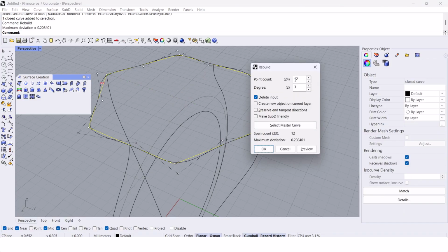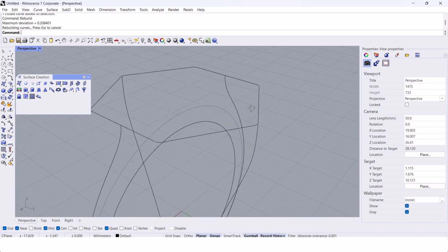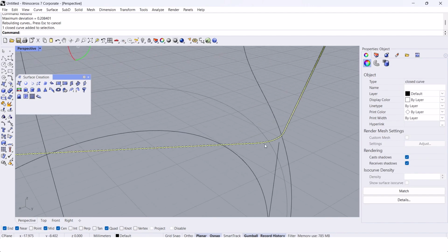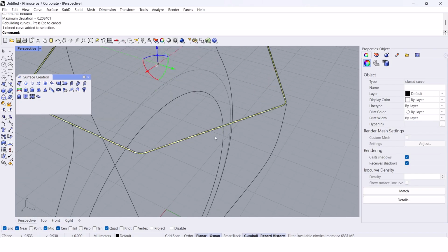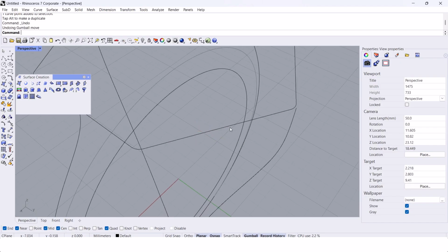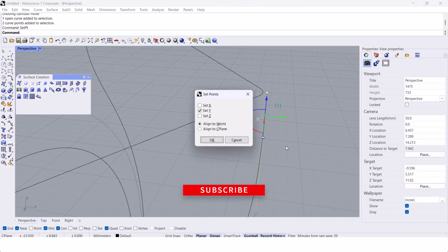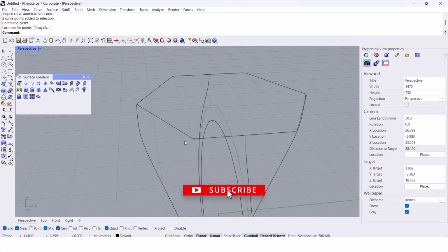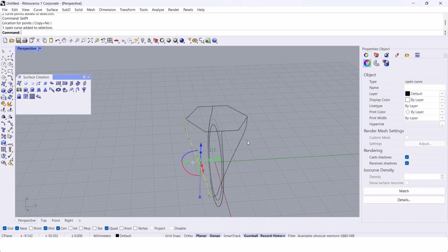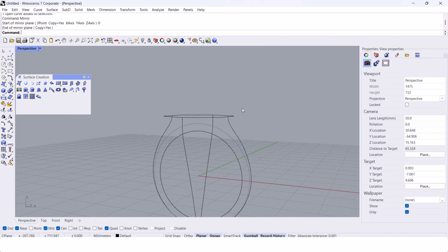Then I'm going to rebuild it with, for example, 1000 points. But just make sure you have done all the designing and detailing at the top, because after you add 1000 points to the top of your ring, you will not be able to make changes, because it will be very difficult to handle 1000 points on the curve. So I will manage the control points again. Let me redo this curve because I lost the history. I will mirror it again.